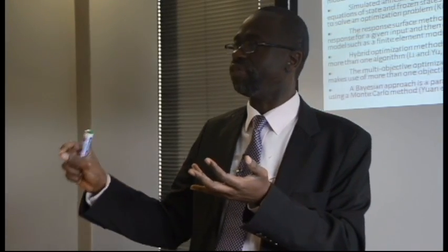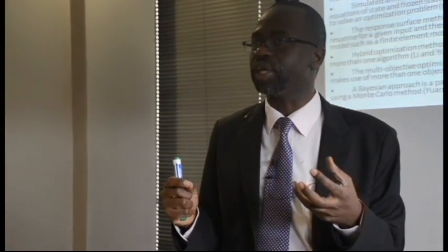I talked about the domain in which you do your finite element updating. Is it in the time domain? Is it in the frequency domain? Is it in the time frequency domain? In fact, if you do your finite element updating in the time domain, it turns out that the prediction you make using that finite element model on data in the frequency domain will not be as good as the prediction you make in the time domain. So the prediction depends on what domain you used to update your model.